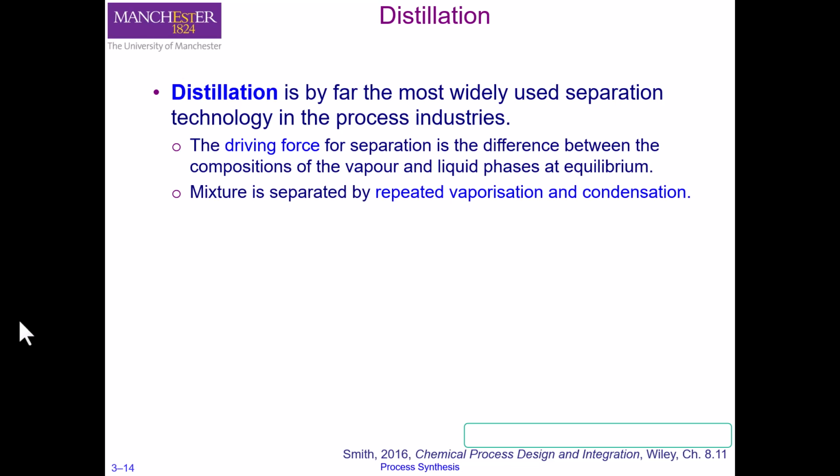Distillation is very commonly used if you have a liquid feed that has a tendency to vaporize as well. Normally, heat is used to vaporize the liquid, and it is very effective if you have a component composition of 10 to 95% of your stream. Distillation is very simple to upgrade as well. It requires low capital cost, and you can scale up very easily. Compared to, for example, membrane technology, it is much more effective, because with membrane technology it is very difficult to stage up or scale up.